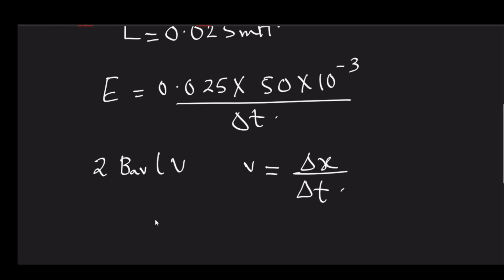So what we can write that B L delta x is equal to, now see, this actually gives us the actual flux, and if delta x is the width of the commutating region, then how to get delta x, that is D by 2, or D is the armature dia or machine dia by 2 into the angular span of the commutating region, that will give you delta x.